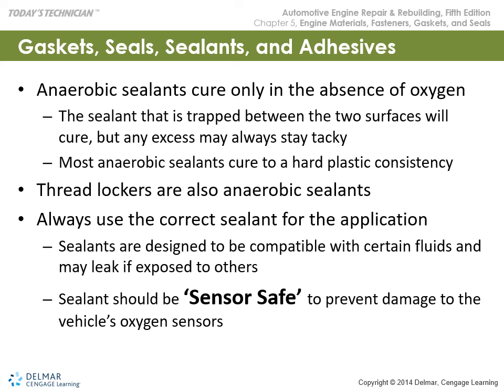And you must pay attention because Loctite has strength ranges. It's got to be called out by the manufacturer. If you're using red Loctite and you have to get it out, you generally have to use heat to get it out. So just make sure that it's called out and that it's sensor safe, because you have oxygen sensors and mass airflow sensors that are expensive sensors, and they need to be utilizing the specified sealant.